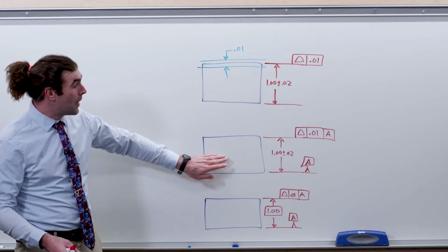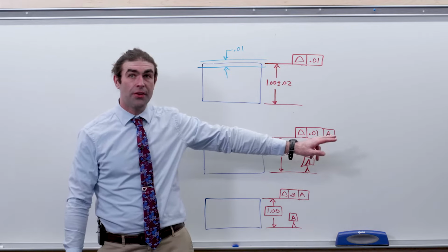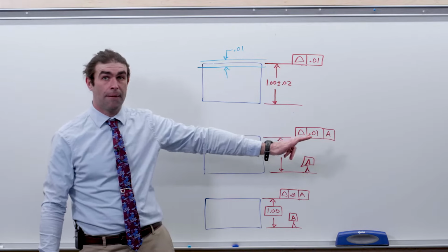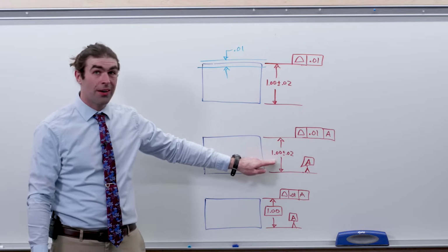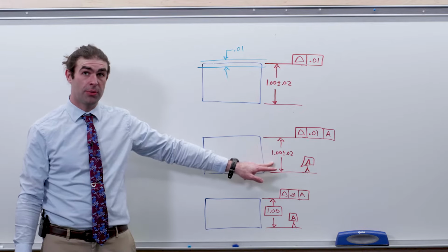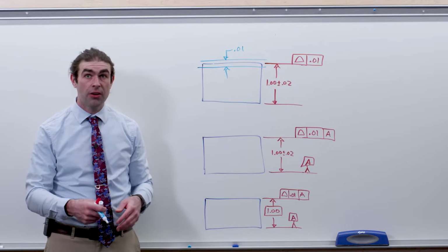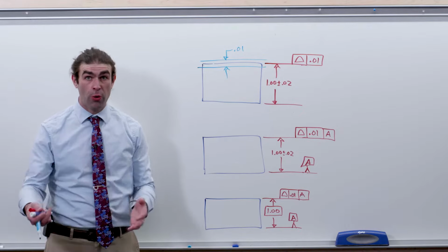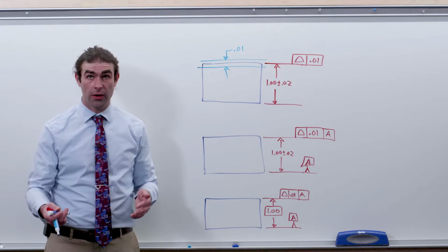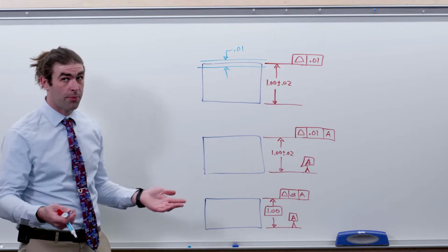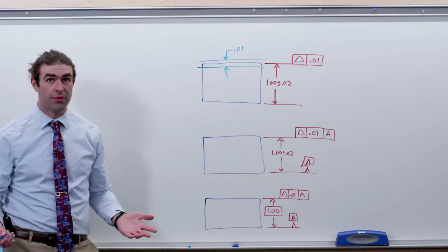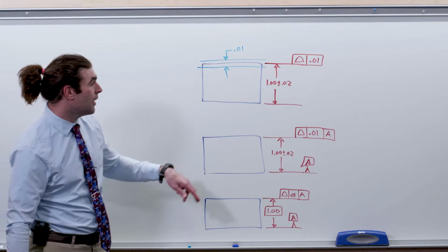The next one, we're going to use a profile of 10 thousandths to datum A. Now, what's important here is that we have a plus or minus dimension. Now, this isn't allowed per the current ASME standard. I'm putting it here to just show you how profile works. It's something you might run into. Not everybody makes every drawing per the current standard, right?